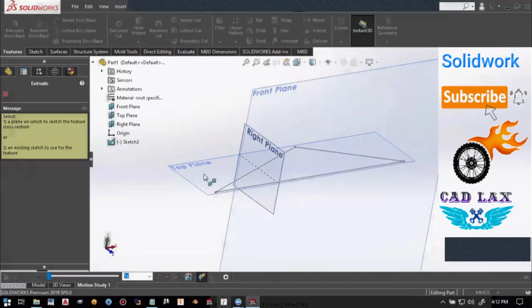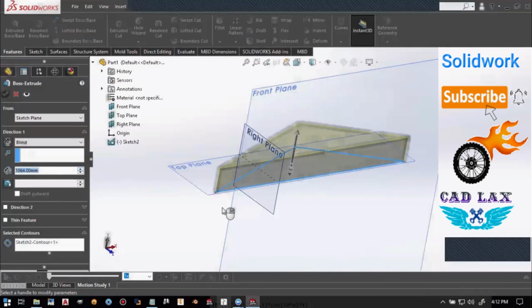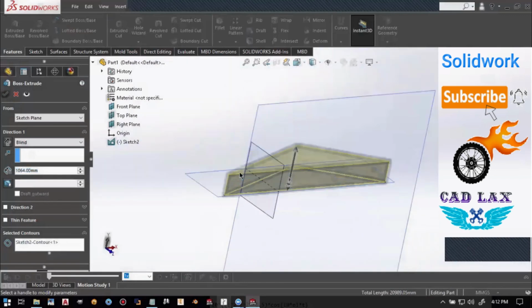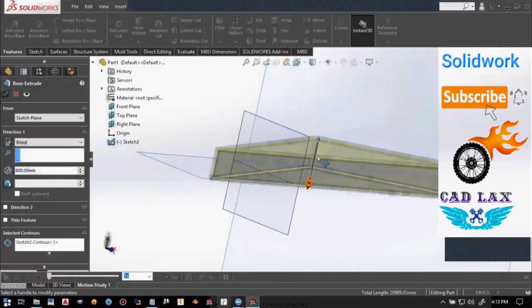If I click on the extruded boss and the sketch, and the value of the extrusion, it means material is filling in the direction of the upside of this sketch plane, top plane, and the height of this we can change from here, whatever height we want. We can also change the direction of this extrusion from this icon.